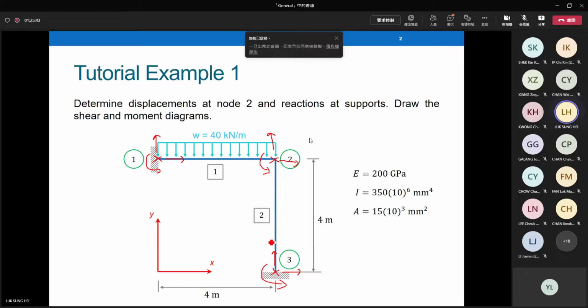You can also assign the member orientation because I did not give you the member orientations in the problem. Horizontal member, turn from left to right. Vertical member, turn from the top to bottom. The member orientation is also arbitrary, right? In tutorial 1, if you still remember, I showed you the effect. What happens if you change member orientation? What happens if you change the code number order? They will not affect the final answer. So you can feel free to assign the member orientation and code number.